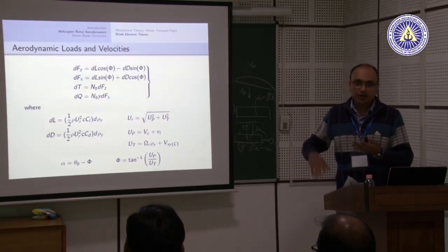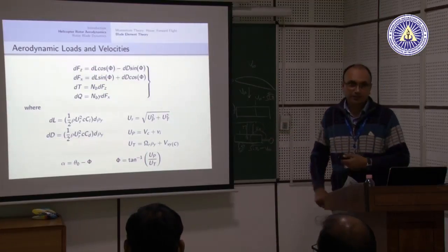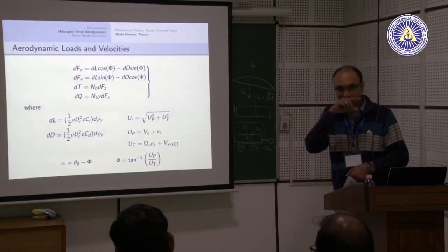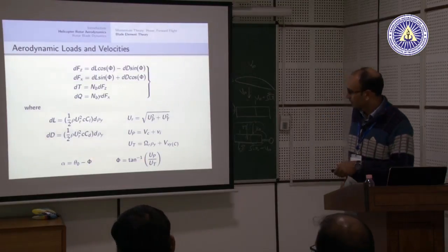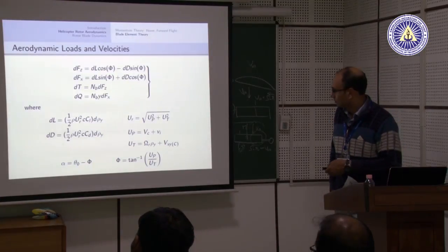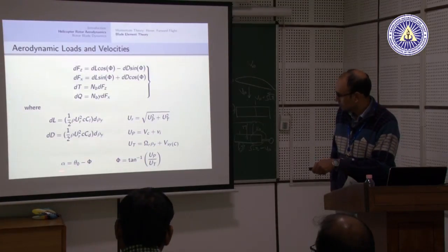This is something you get from the airfoil properties. If I know what airfoil is there on my blade, I can just do a Google search and it will tell me the Cl for that particular airfoil as a function of alpha. Similarly, I can get the Cd for that airfoil as a function of angle of attack alpha, which you saw earlier.